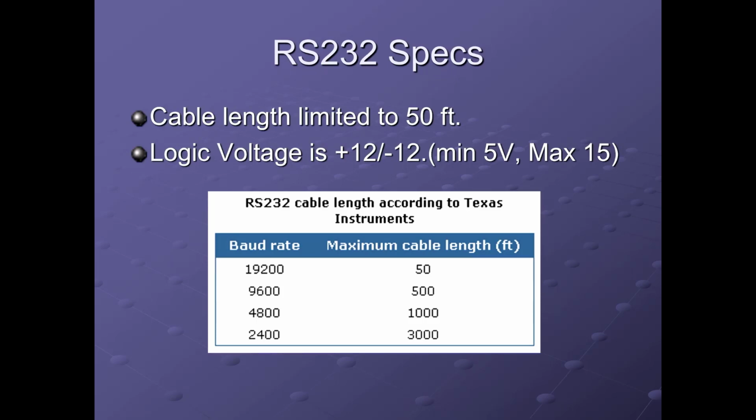So just to look at some RS-232 specifications, when we look at this table, this is the maximum official baud rate for RS-232. And this is the maximum cabling distance for RS-232. Now, if you look anywhere for specifications, you'll always find they're based on worst case scenarios. So why do I say that? Well, because of the technology that's improved for the manufacturing of data cables, because of devices that are better at processing data over a data line. You could really say that this is an under-spec'd value, that with devices and cables nowadays you could take this far beyond that. But this is still officially the maximum data rate of 19.2 for a baud rate and the maximum cabling distance.